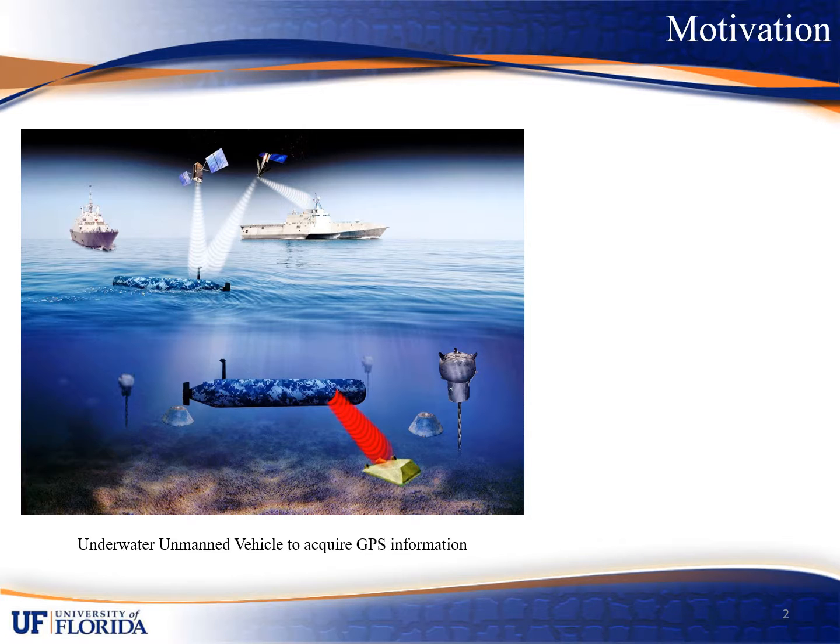Then, what if you can stay submerged underwater indefinitely without surfacing, but can also acquire GPS or state information from another agent? This other agent, what we call a relay agent, acts like a ferry, which will provide state estimate information to the exploring agents. In this case, the UUV can stay submerged at all times, and we call this method a relay explorer approach.